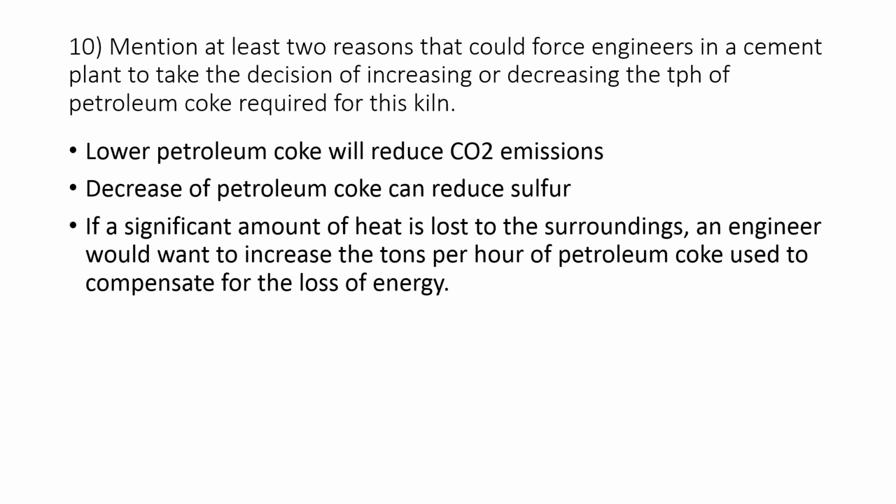Then our last option would be if a significant amount of heat is lost to its surroundings, an engineer will want to increase the tons per hour of petroleum coke used to compensate for the loss of energy. It will be something not to decrease, but to increase. The question doesn't ask to decrease or increase specifically, it asks what would happen in both cases. So these 2 would be to decrease the TPH of petroleum coke, and this one would be to increase the TPH of petroleum coke. So both options are available.